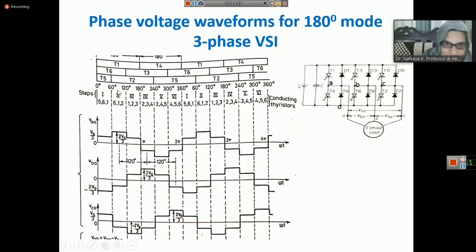Similarly, in the 6-1-2 period we can see 2 bottom thyristors, that is thyristors 6 and 2, so you will get minus VS/3, minus VS/3, and T1 as 2 VS/3. The limb which is connected to only one thyristor has 2 VS/3, and the others have VS/3. Actually this needs a detailed description with tables and the equivalent circuit of each interval.